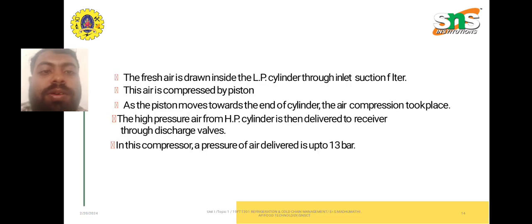As for the working principle, fresh air is drawn into the LP, the lower pressure cylinder, through the inlet filter. This air is compressed by the piston. As the piston moves towards the end of the cylinder, the air compression takes place. The high pressure air from the HP cylinder is then delivered to the receiver through discharge valves. In this compressor, the pressure of the delivered air is up to 13 bar.